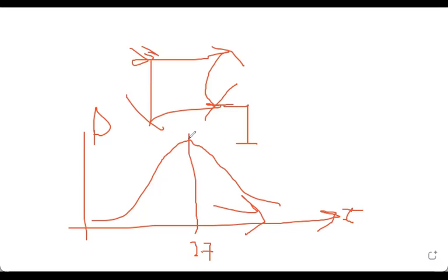Again, each photon generates an electron, that's true, but don't forget that the extra energy greater than Eg turns into thermal energy. So when you increase the number of photons reaching the solar cell, of course you increase the number of electrons, but you also increase the temperature. And herein, another very important parameter starts to dominate, which is temperature. So back to the slides.